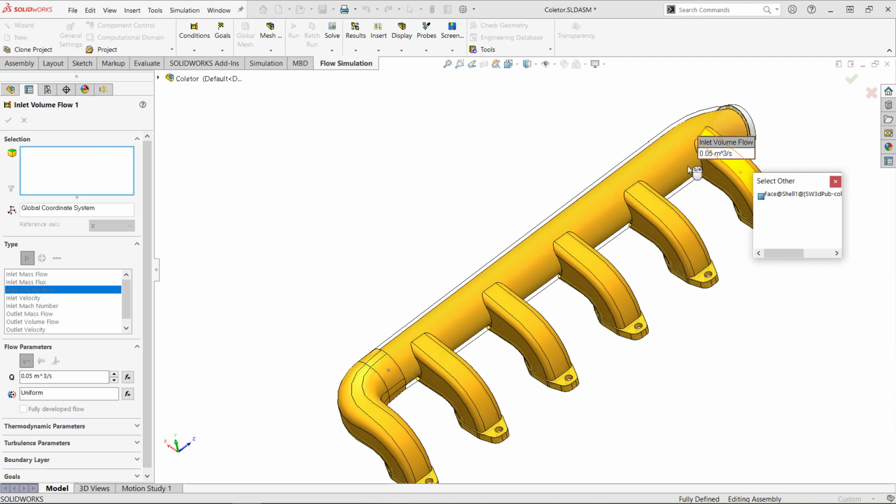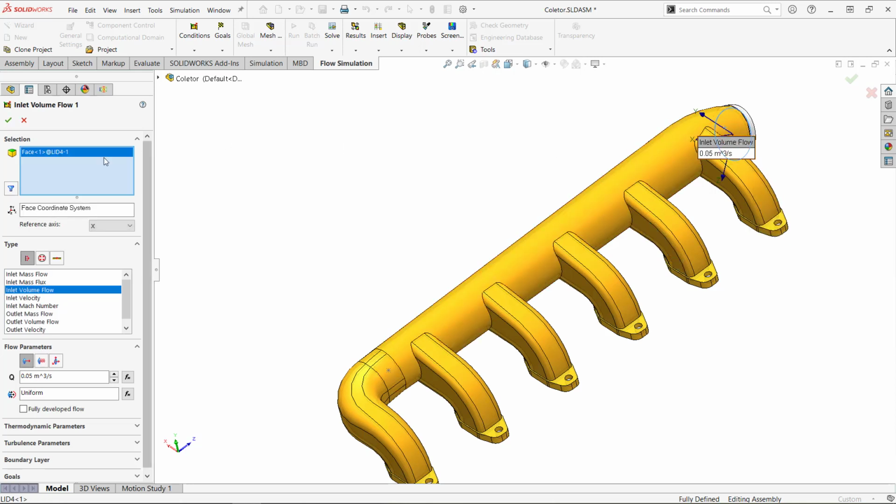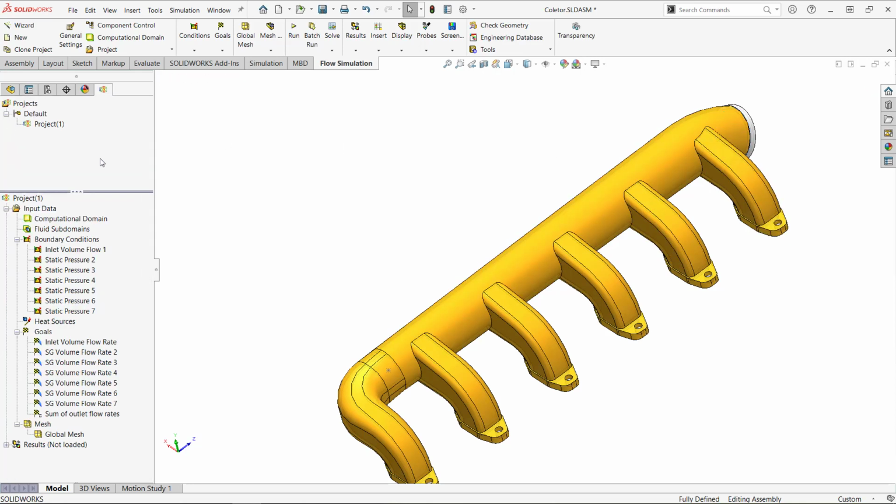Now the idea here is I'm going to right-click once again on that particular surface. This is the inner surface of this particular portion of the model. When I right-click again, it's going to hide that, and now I have access to the internal surface. But the idea here is I can continue to right-click on things to hide any portions of our models and continue to dig into our models until we expose the desired surface. So for me, I'm going to select this internal surface of the lid and click OK to finish that. So that's the Select Other functionality.